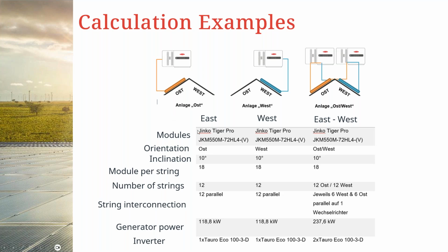So this was actually brought into context with this particular investigation or research that was done with particular systems connected on a roof. Some were connected on an east-facing orientation to one inverter, as you can see. And then other modules facing west were connected to another single MPPT inverter.